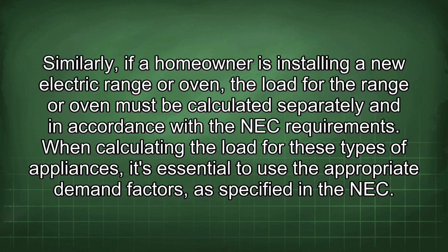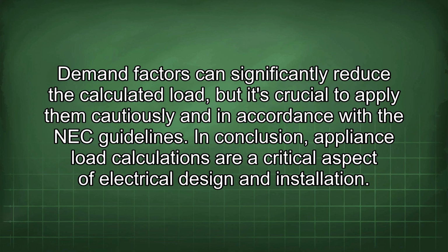When calculating the load for these types of appliances, it's essential to use the appropriate demand factors as specified in the NEC. Demand factors can significantly reduce the calculated load, but it's crucial to apply them cautiously and in accordance with the NEC guidelines. In conclusion, appliance load calculations are a critical aspect of electrical design and installation.